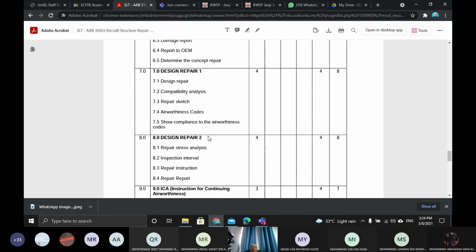And then we go on to analyzing the load. What are the loads that have been lost? What load has been recovered? From the load, we also need to calculate the stresses of the repair, for each part, component, and area of the repair, and from there we compare with the material strength. For the repair to be approved, you need to assure that the stresses from the load on the repair will be less than the material strength. So we have to have at least a 50% margin.